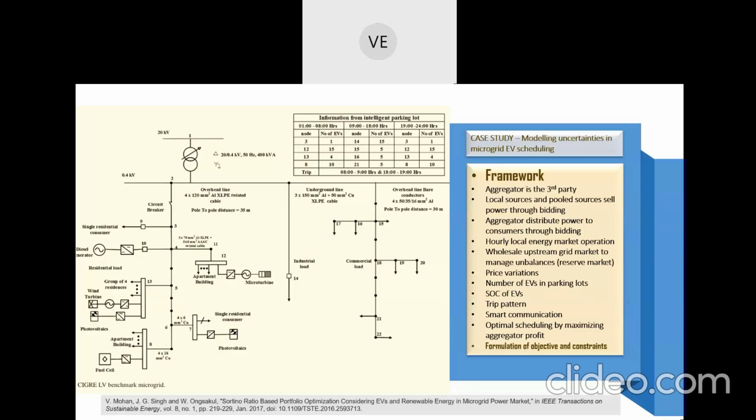Before that, if it is cost minimization, then you should frame the cost function as a function of independent variables, active power dispatch from each of these sources. Because when active power output from these sources vary, accordingly the operational cost is varying.